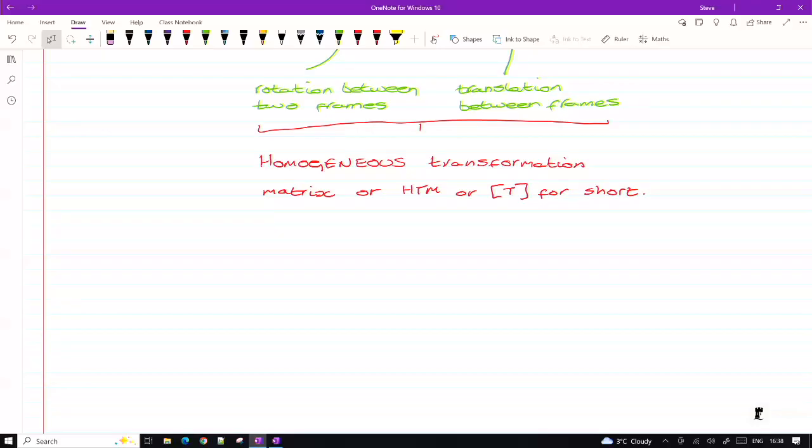So I'm just looking, I've got several examples to go through. I'll do the first one, then we'll call it a day. It shouldn't take too long because it's a simple 2D planar arm, but we're going to apply this approach to that. For a 2D planar, so for a robotic system, when you move in between frames, you come up with a homogeneous transformation matrix for every set of frame transformations. So in a 3D system, those matrices could be different. Okay, so you have a whole series of them. For a 2D planar arm, they're always the same because you're always rotating within the plane of the board.